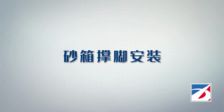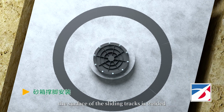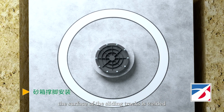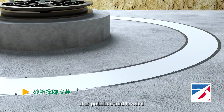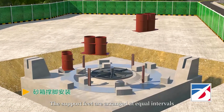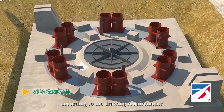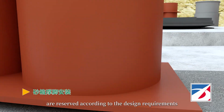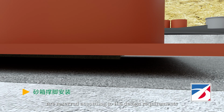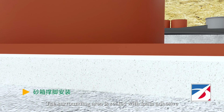Installation of sandboxes and support feet. Before installing the support feet, the surface of the sliding tracks is welded with stainless steel plates in an intermittent manner. After welding, it is polished and leveled. The support feet are arranged at equal intervals according to the drawing requirements, and the gap between the support feet and the sliding tracks is reserved according to the design requirements. The surrounding area is sealed with foam adhesive.